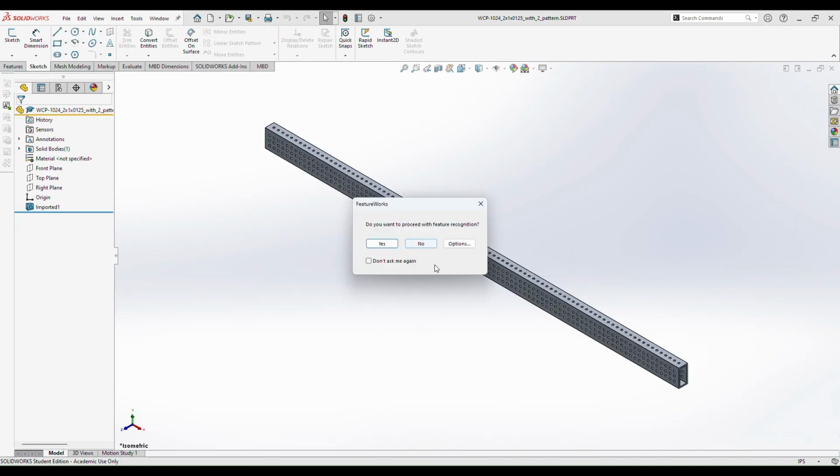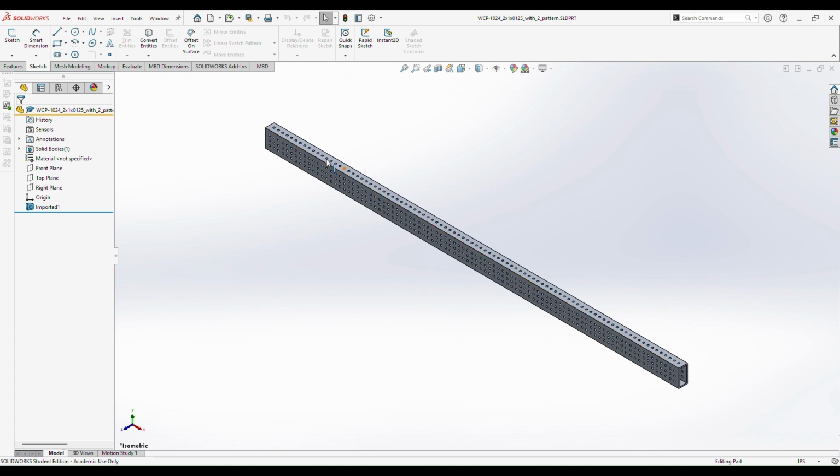You might say, oh, let's take this and we'll cut it down to length in here. Well, if you do that, it means that that's linked to there forever. You'd say, well, I want to have one of those tubes as another element on the robot, and you wouldn't be able to do that. So instead, we're not going to modify this part. I just opened this part in order to get it open so that we can do inserts with it. Instead, we're going to make another new part.